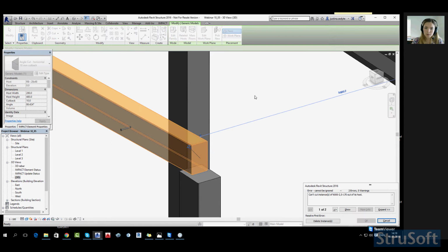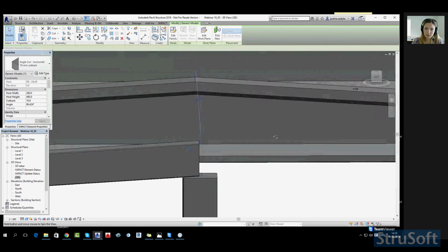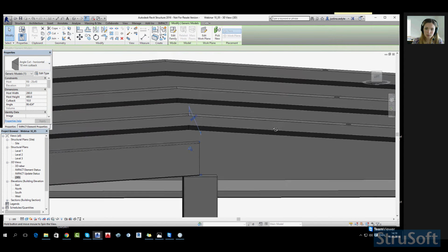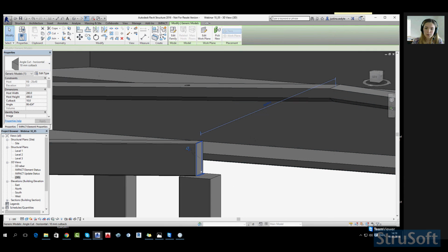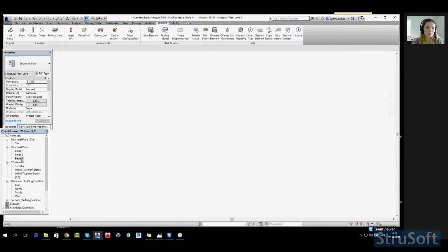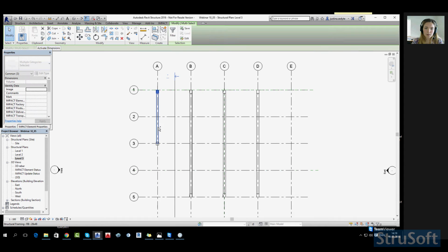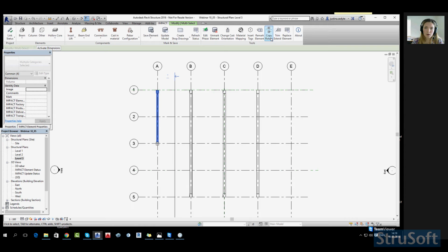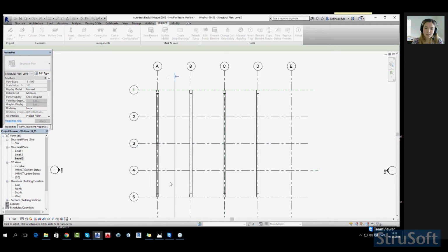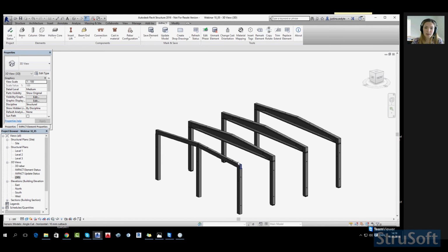update lifts. But now I see that I have actually to rotate it. So I just go for the shortcut RO and maybe rotate it 90 degrees. Okay, now it's standing like this. It is actually straight in one line with the other sloped I-beams. You can also set a cutback. Right now it has 10 millimeters. And now just simply go to the level 3, take those elements, copy and rotate, take the middle axis.